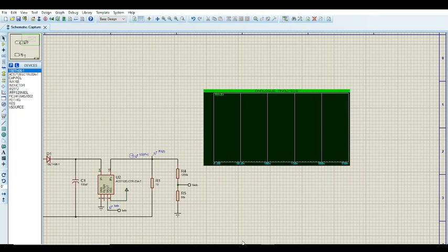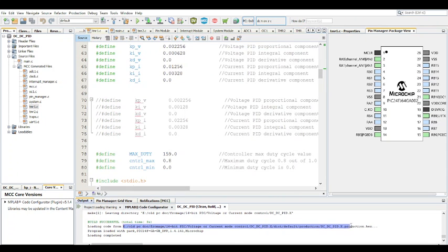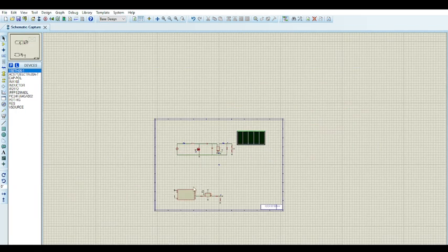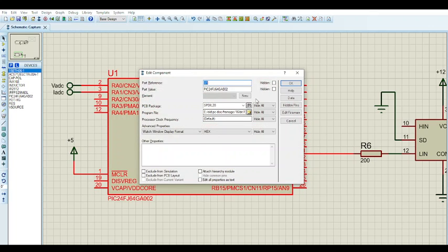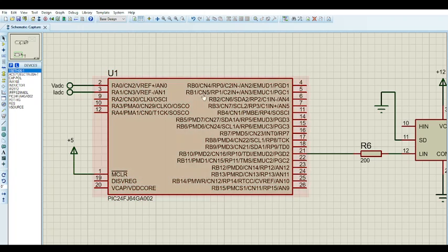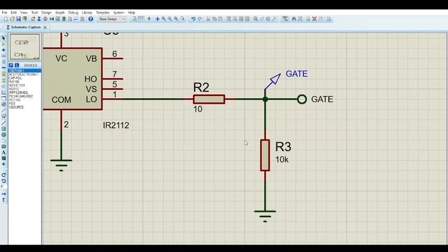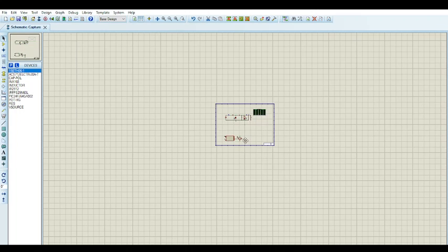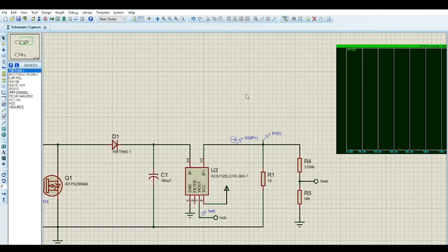So now I'm just gonna run it, make sure that it's running this particular one, and go to the controller there. This particular controller is operating at 32 megahertz, and obviously this is the gate, 10 kilo ohms gate resistor, pull down resistor. All right, so now I'm just gonna run the SPICE analysis. Might take a couple of minutes. All right, it's going really fast. I don't know if that's a good or a bad thing. I guess I'm gonna see based on the results.